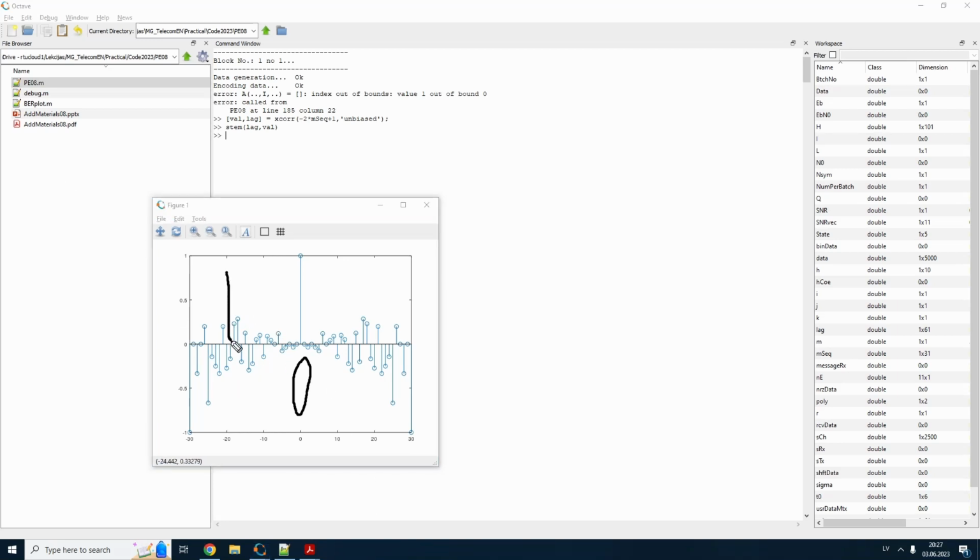There were maximums somewhere here, somewhere here, and so on, multiple maximums of the same size. Now for a real M sequence, the maximum will be only one, at lag 0. That is the property of an M sequence. So that is a test to prove that it actually has randomness in it. The ideal autocorrelation function, of course, would look like this: 1 and all the others would be zeros. But since we didn't repeat the sequence periodically, you can even see that at lag 30 it's almost maximum again, because only one symbol is compared.